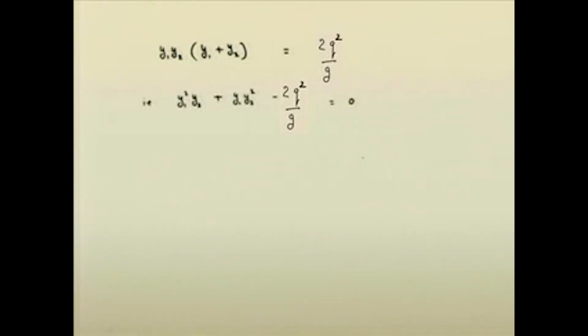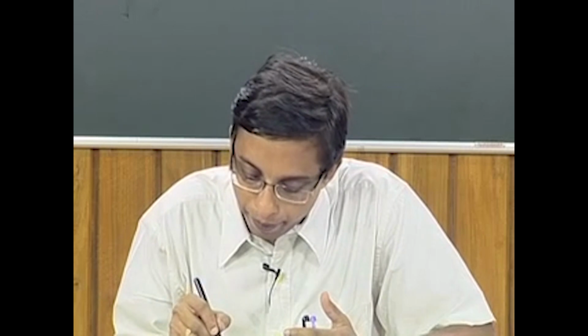We do not know what the post jump depth is, because the pre jump depth we already have. It is we who are releasing the water either from a sluice gate, or allowing the spillway flow over the spillways. So, we know the pre jump depth mostly, and we want to identify the post jump depth. Based on those manipulations, let me suggest this as a quadratic equation in terms of y 2, the post jump depth.